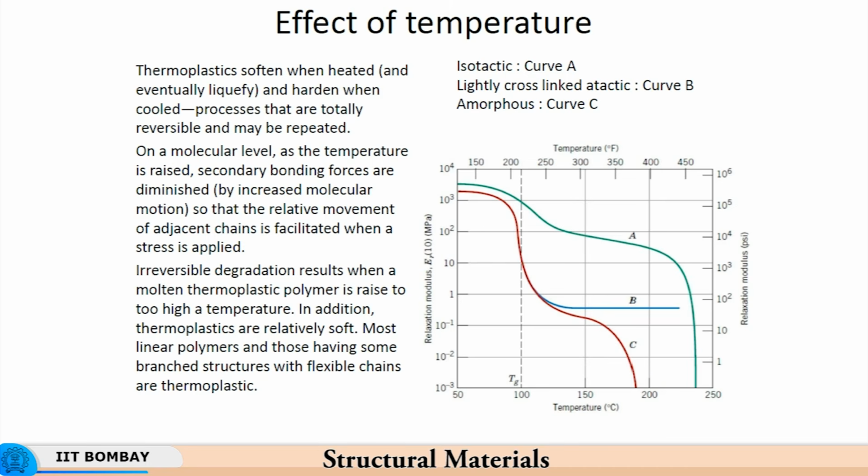For a fresh polymer you will need polymer of a certain molecular weight, but this degraded polymer would have a distribution of very low molecular weights, and that will pull down the properties of the fresh polymer which you might have planned to use.